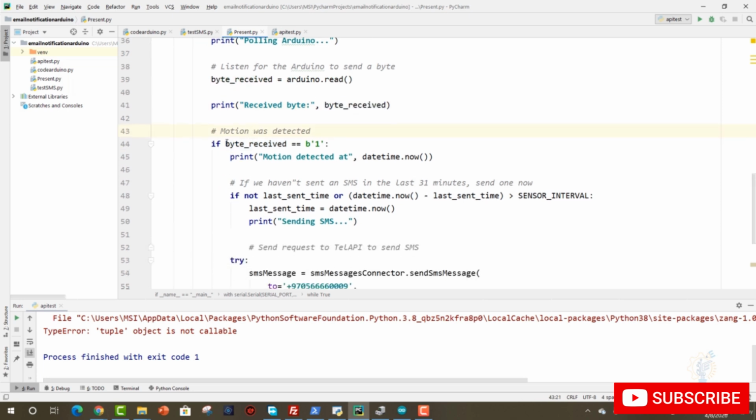And here we are checking if the byte received that we just stored equals 1. We already mentioned that inside our Arduino code we send 1 and turn on the LED when motion is detected. So it will print motion detected at, and will print the date and time.